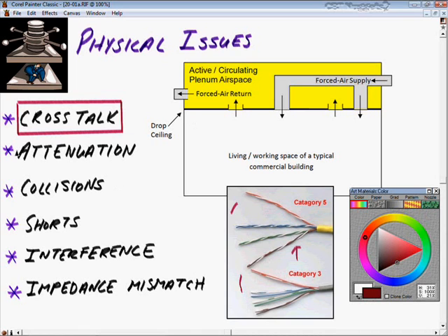And the other thing is attenuation. Okay, it actually has what we call rapid attenuation, so your cabling distance is limited to hundreds of meters. Coaxial cable, for example, has moderate to low attenuation. So if you use, let's say, repeaters, you can actually extend the distance to thousands of meters. To mitigate against the attenuation problem as a troubleshooting solution, you could implement fiber optic cable, for example MMF, and that will give you extremely low attenuation, or loss of signal. And you can support distances of up to 2 kilometers.